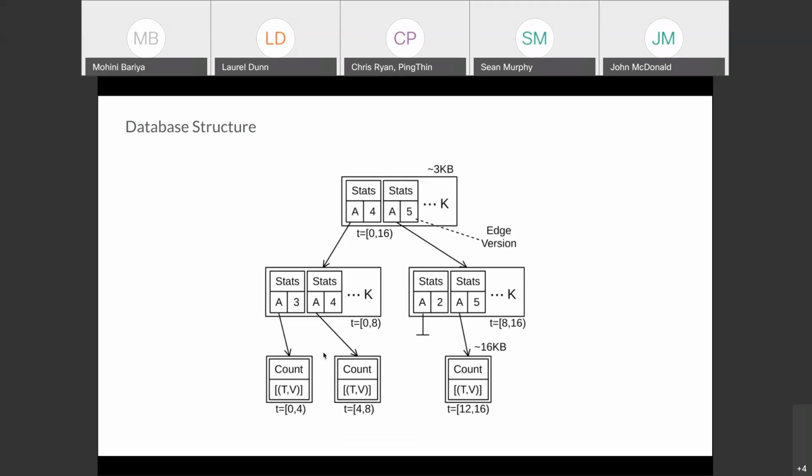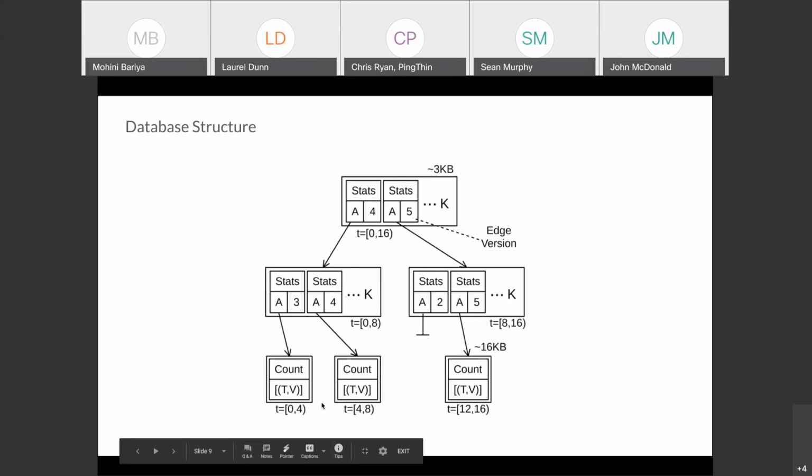So if I'm looking for extreme values, which is what I'm looking for when finding voltage sags, this structure makes it really efficient. I can look at the summary statistics over a large window, and consider the minimum in that window. And only if the minimum meets my criteria of being under a certain threshold, only then will I go down all the way to the high resolution raw data to retrieve the voltage sag.